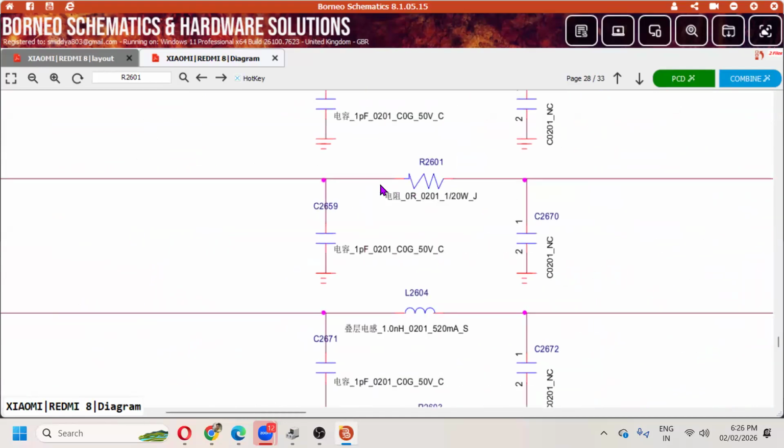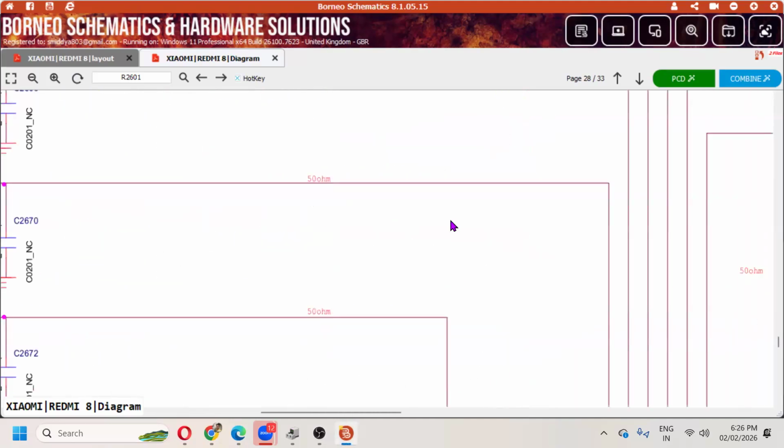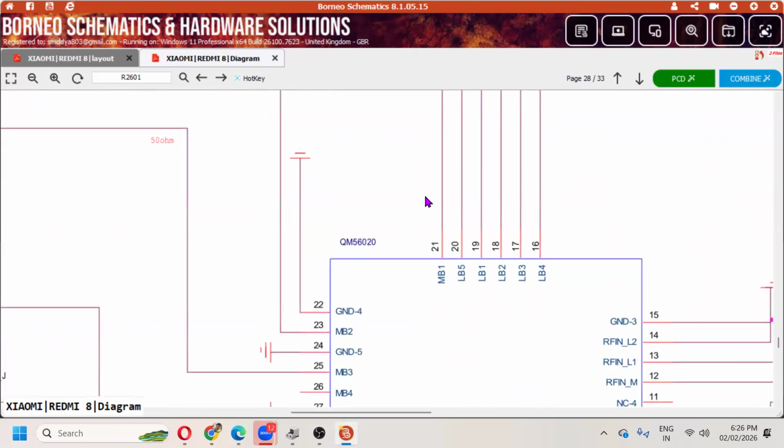If the company wants, they can make this directly, but they don't make it directly. Why? If over voltage comes here, then this resistor gets damaged and protects the related IC. That's why the company puts these types of 0 ohms resistors in the line.